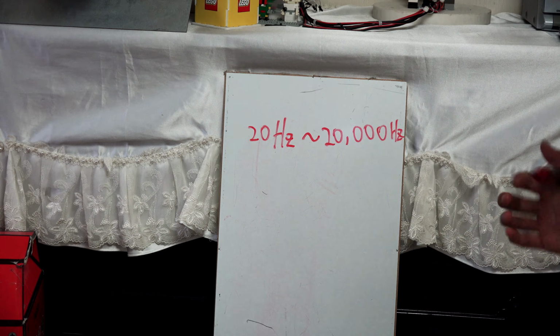So after that we can divide the duration by the 58 that we calculated before, so we can get the distance in centimeters. So I uploaded it, so I will show how it really works.